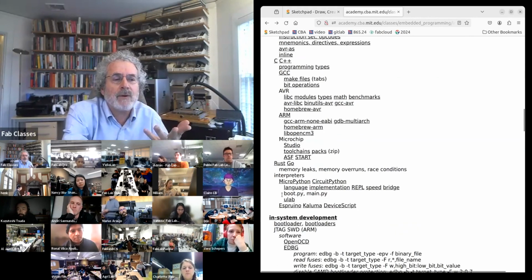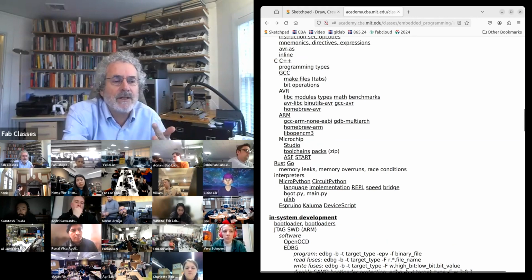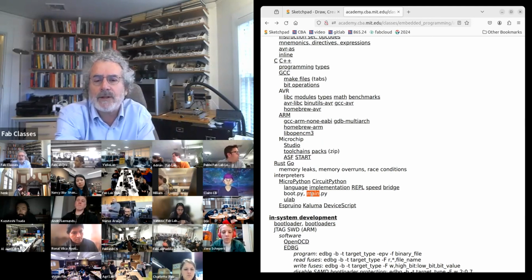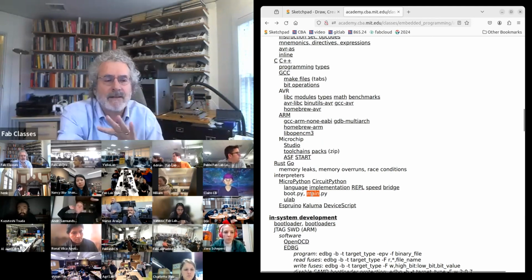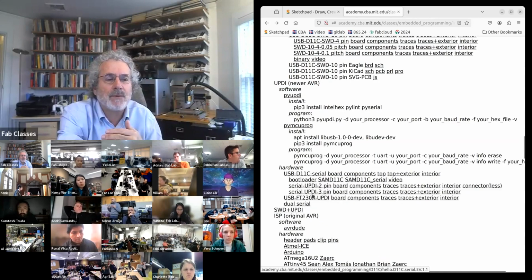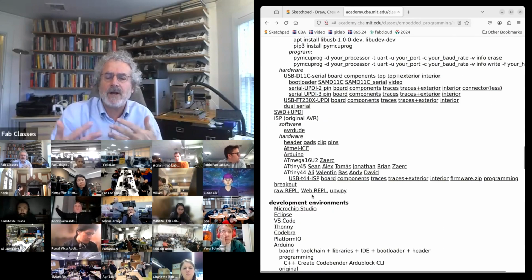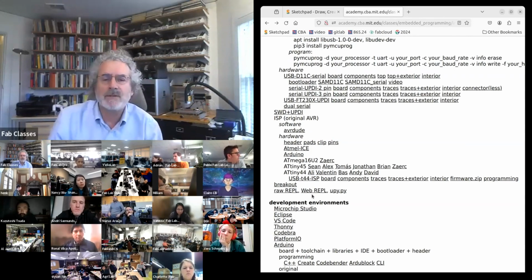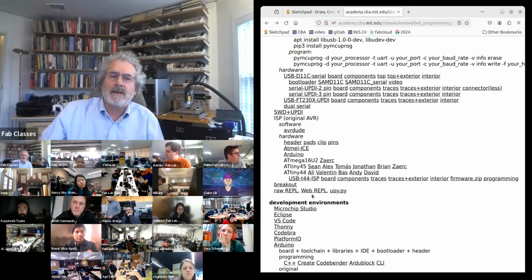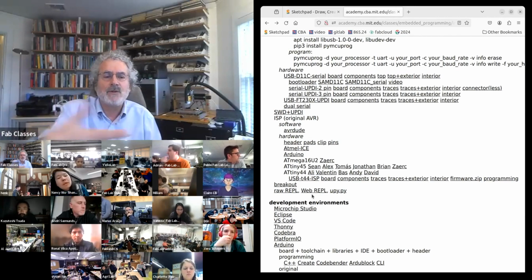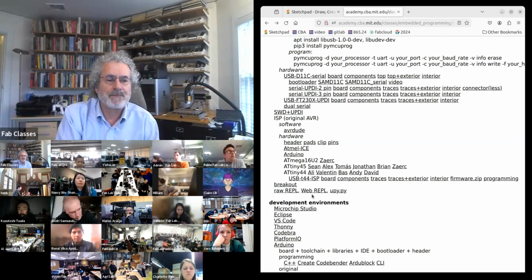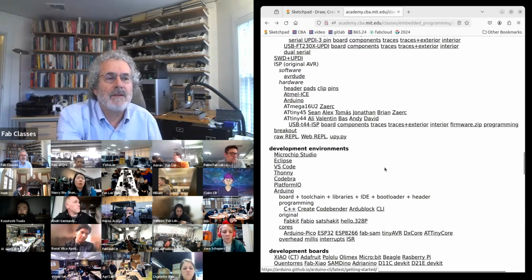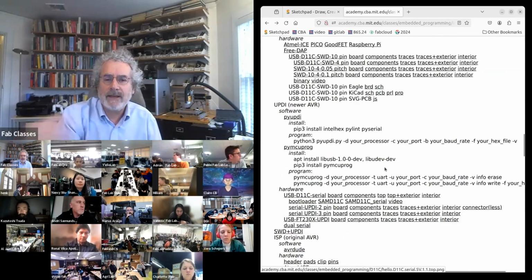But in MicroPython, when you turn it on, it first runs a program called boot.py. And then if you save a program called main.py, it'll run that automatically. So you can run programs in Python with the interpreter, or you can save them and they run the next time you turn it on. So there's no notion of the programmer needed. You're just using this interface to load the code into it. So that's how we're going to get programs into our processor.